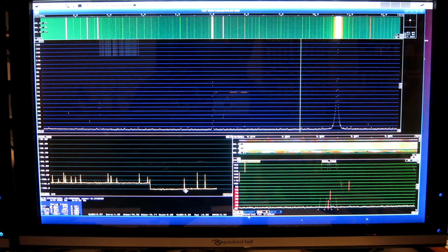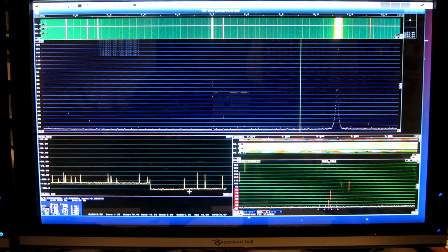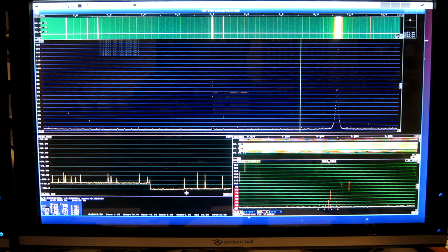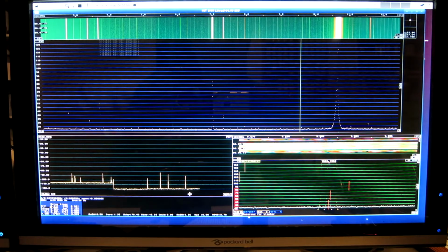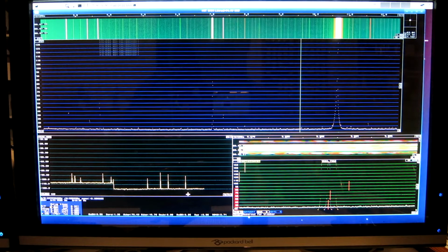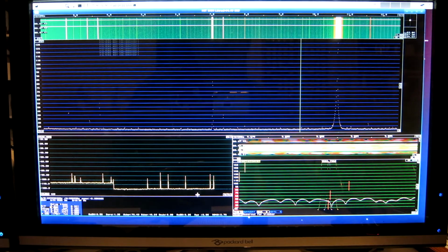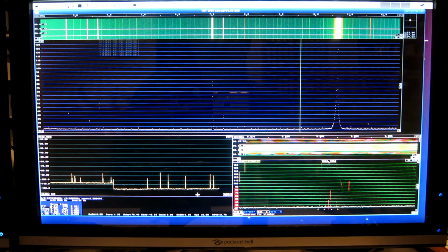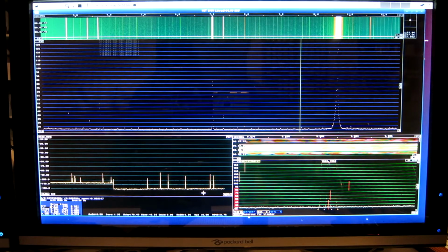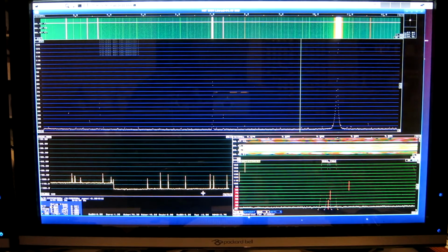There isn't any phase noise on the sampling clock that adds noise at a distance of 1 megahertz. So it looks like this sampler is perfectly okay as a radio receiver.